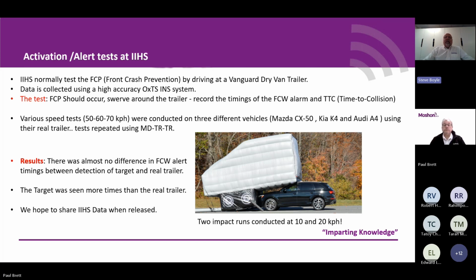We went further and tested one of the cars that seemed to want to brake. We started at 10 and did an AEB stop at 10, and carried on up to 70 kph, doing a full AEB stop at the trailer, and the car successfully did that. They tried a couple of the other cars to do the same.